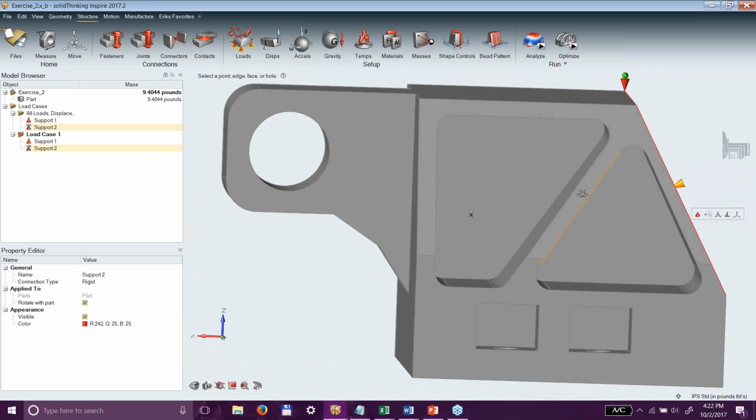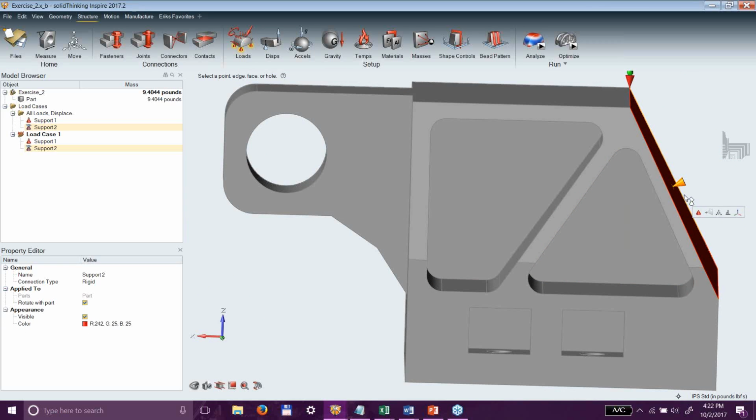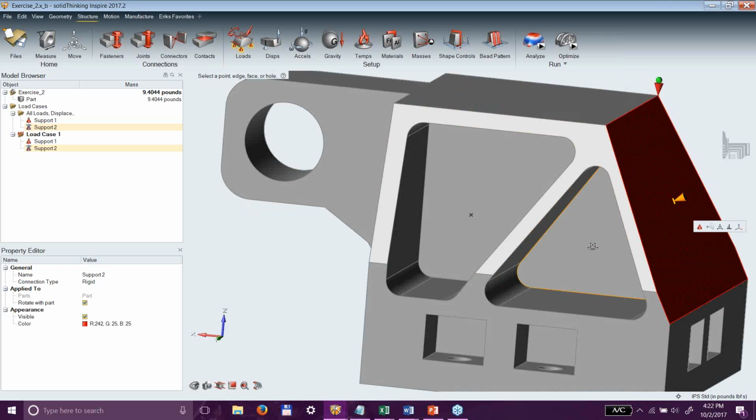You'll notice that that constraint has been created normal to that surface. To do that traditionally, I would have to create a local coordinate system, assign it to the nodes on there, and then assign the axis to those nodes so that the constraint would take that orientation. But with here, it automatically did it.